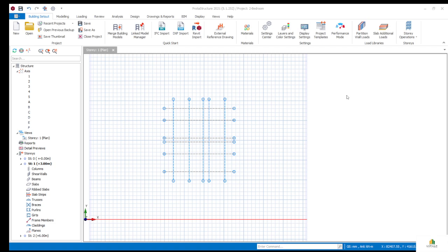After you have selected the one in story 1, which shows light blue, you hold your shift, and with the left button of your mouse held, you drag it down to select it. Because we want all the columns to be the same, the moment you place a column in story 1, it will appear in story 2. On that edit story dialog box, you see impose load reduction. Don't go to that place.